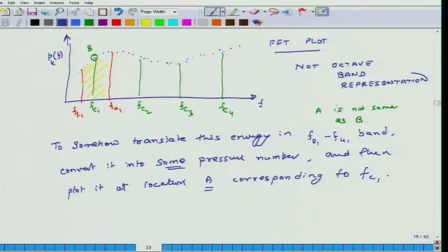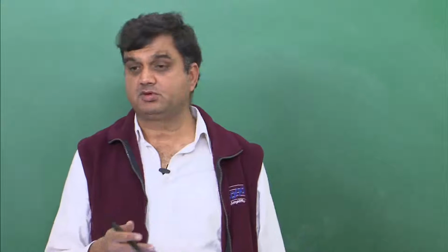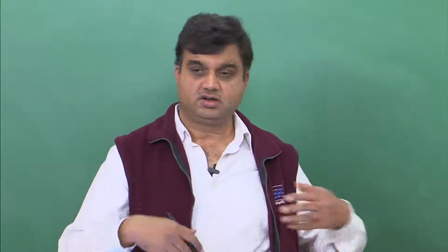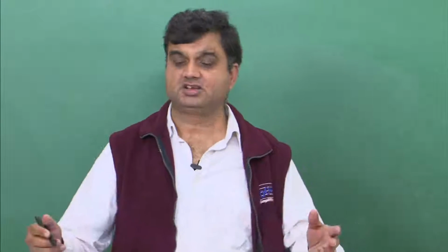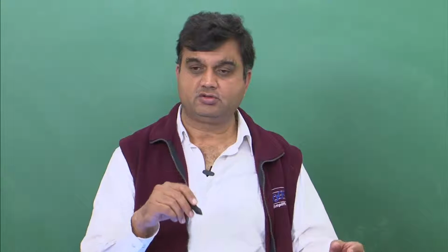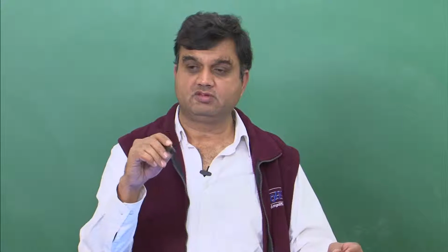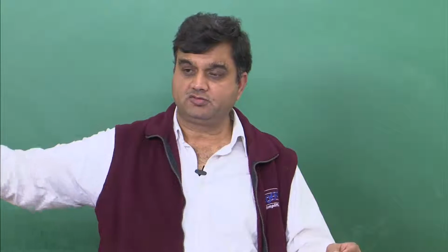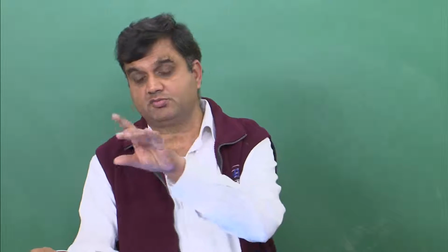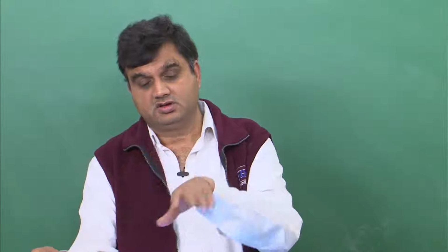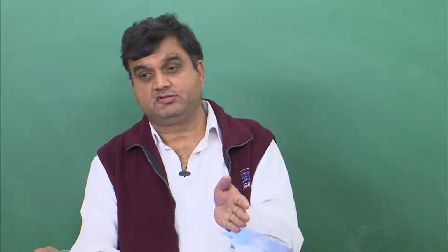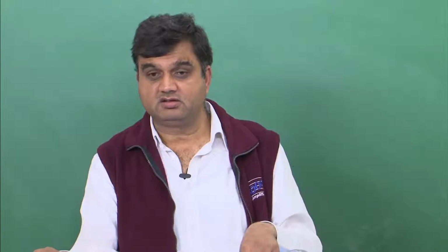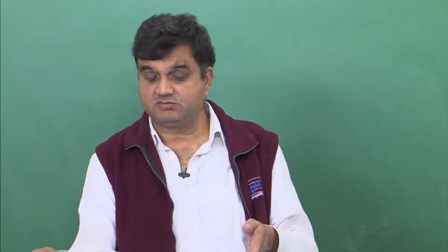So it will be important to learn to go to MATLAB and explore what is the MATLAB function for the band pass filter, test it, create an artificial signal. What you can do is y equals a1 sin(2 pi f t), and you put in all the frequencies, so you know how much energy you are putting in for all the frequencies, and then you can put the filter, and calculate the decibel value of that using this method which I am explaining to you.